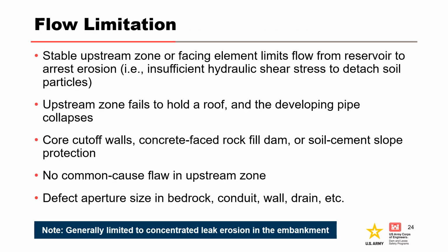Factors to consider when assessing upstream flow limitation are shown on the slide. Concrete or sheet pile walls within the embankment or that fully penetrate the foundation soils greatly increase the likelihood of the flows being limited. Modern concrete barrier walls, crossing the internal erosion pathway, typically extending into rock, that are in good condition, have the best chance for success. Steel sheet pile walls may be less effective under poor driving conditions or poor construction techniques.